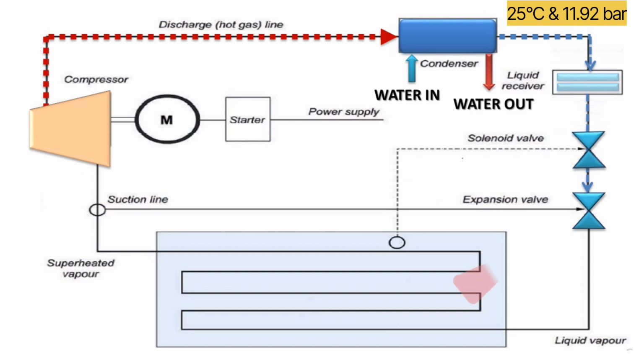The expansion valve is the throttling device through which the refrigerant flows from the high pressure side to the low pressure side. Due to the pressure drop, the boiling point of the refrigerant comes down and it starts evaporating. The latent heat comes from itself and its temperature drops to about minus 35 degrees and 1.2 bar.